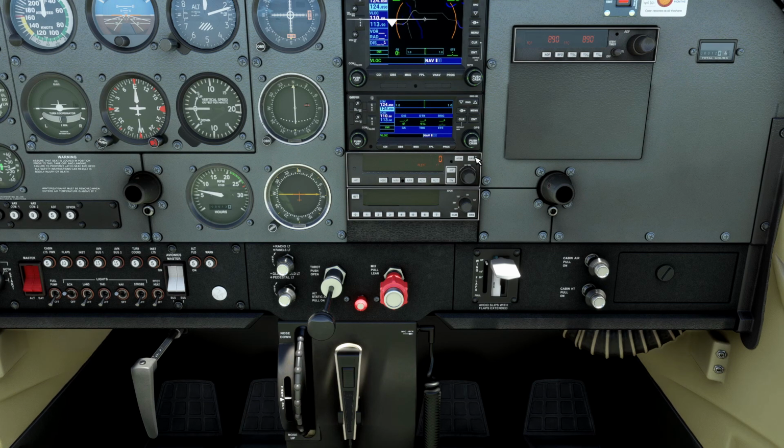There are a couple of good practices to use before you take off with the autopilot, though, to have it set up and ready to go once you get airborne. The first is to set the altitude either that you're initially cleared to or you're initially planning to climb to in the altitude pre-select field here. That will get you set up for when you want to turn the autopilot on, and it will also serve as a reminder of what altitude you're cleared to.